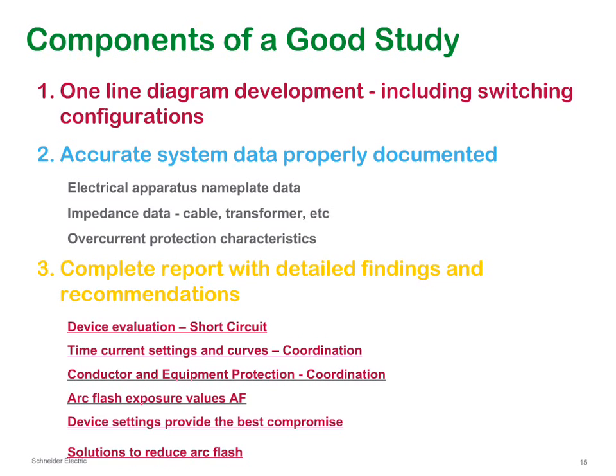And if we just go ahead and collect the data, run the study, calculate arc flash energies, and then label the equipment and walk off the facility, we've done the facility a bit of disservice in the sense that we haven't done everything we can on evaluating what can be done to reduce the energies. This coordination study is where we really start evaluating the settings on the devices to see how we could possibly reduce the arc flash energies in the system. And it's a very important component of the overall evaluation.